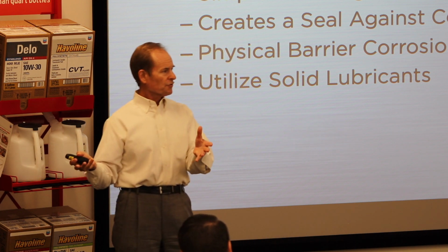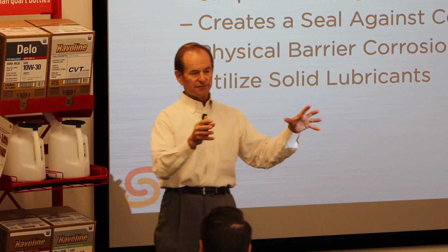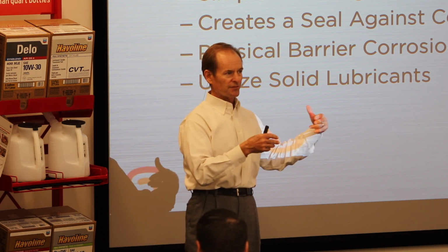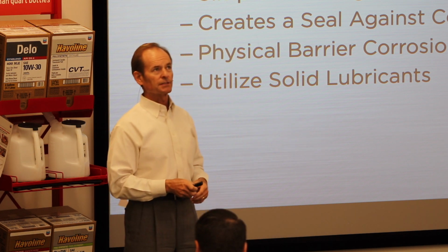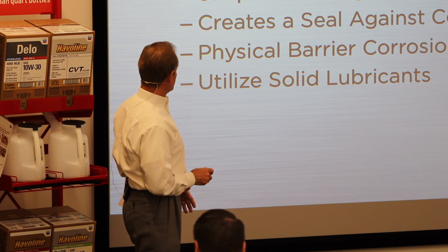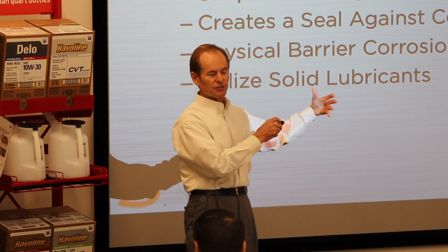But a grease is another story, right? A grease, which is a semi-solid substance, you can disperse this stuff throughout the grease, and it's always there. Your moly's always available to your lubricated surfaces. Okay, so those are our advantages of grease over oil in a comparable situation.